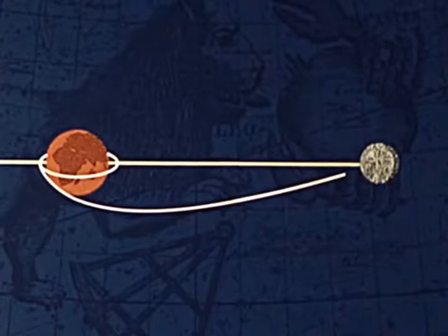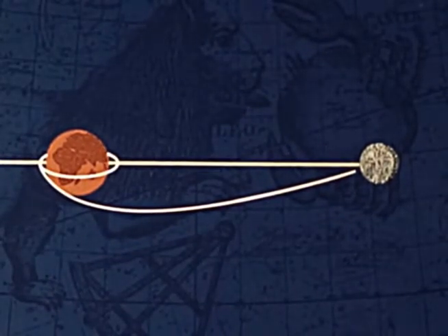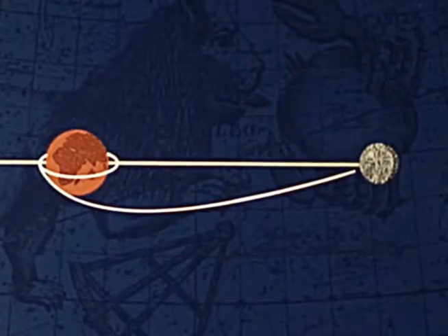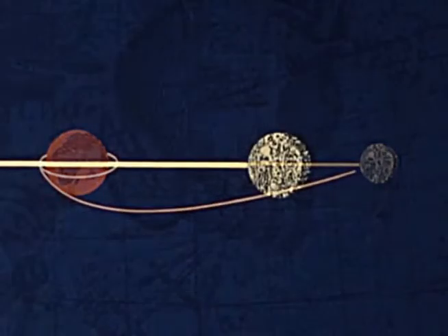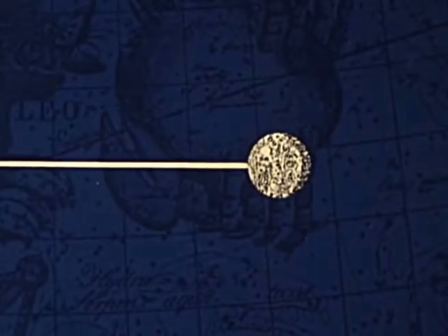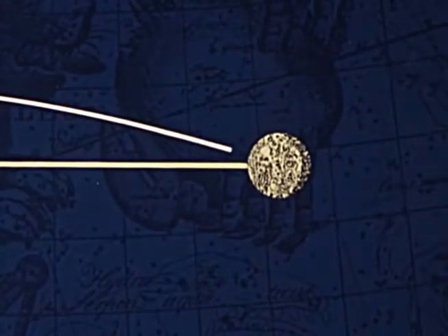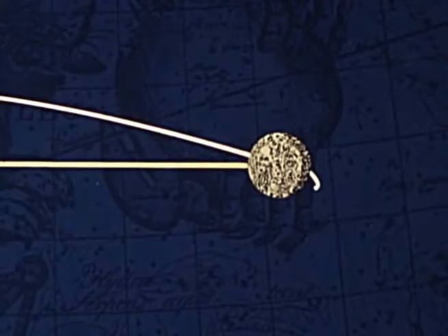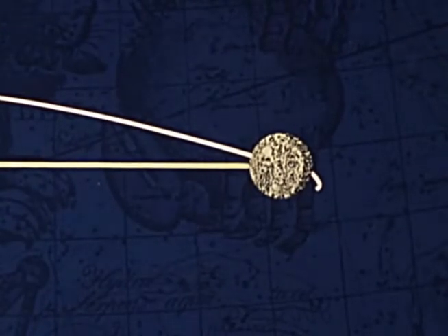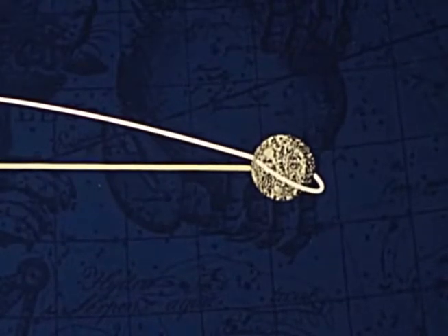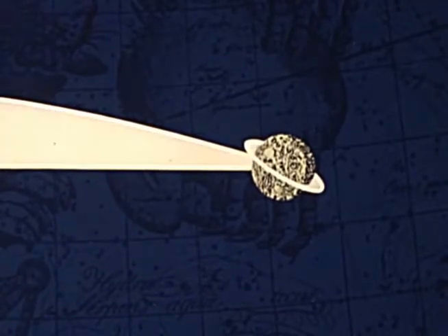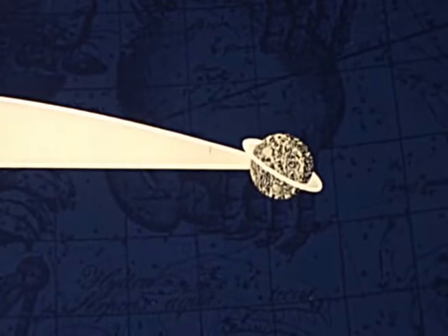The angles of inclination of the translunar trajectory with the moon orbit plane have direct bearing on the landing areas attainable on the moon. Following a Pacific injection, the spacecraft approaches the moon from above the moon orbit plane. This forces the trajectory below the plane on the far side of the moon where lunar orbit injection takes place, and back up to the northern latitudes on the front side where the landing areas are located.